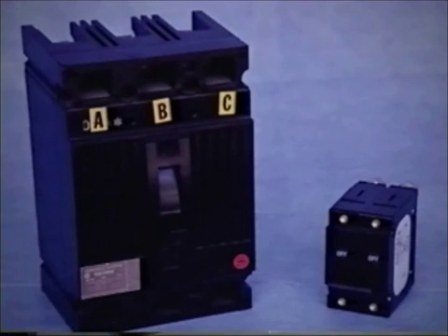However, you must remember that the current demand on any one circuit cannot exceed the full load current of the alternators. The safest method to avoid overloading is to install a three-pole circuit breaker. You can then break down the load into three circuits on the load side of the circuit breaker.